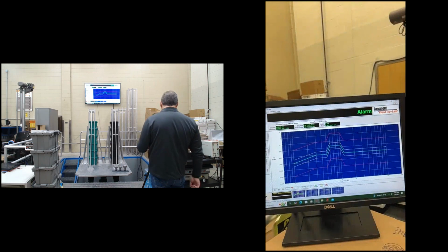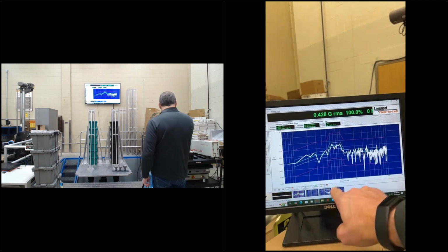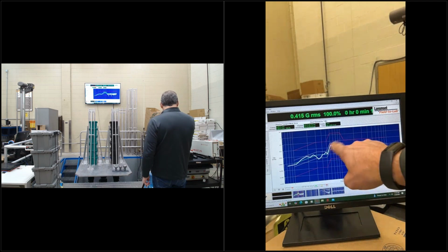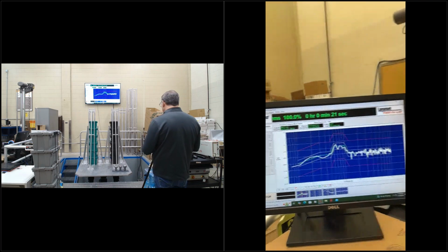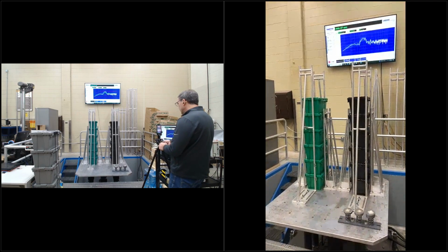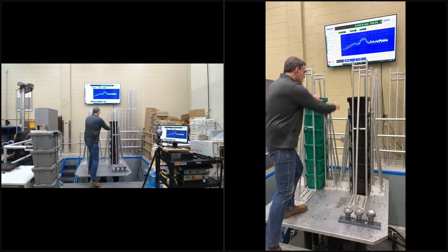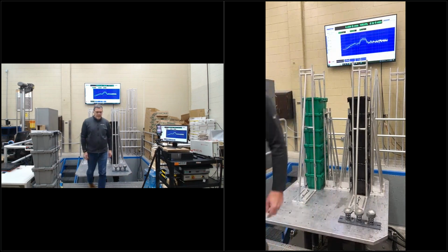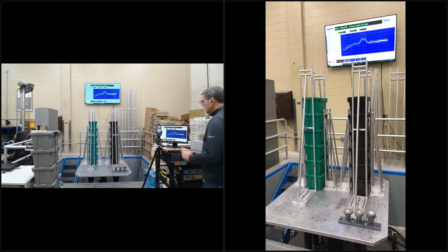Flat profile out to 100 hertz, but I've added this bump in the 6 to 10 hertz range. This little segment of energy. Why did I do that? Well, because that's where those two guys like to think. Different frequencies. You can kind of see the black one shaking differently. They're both kind of bubbling or percolating differently. They're responding differently based upon that energy, but it's all being input there and it's focused, and I'm stressing them by running a profile like this.